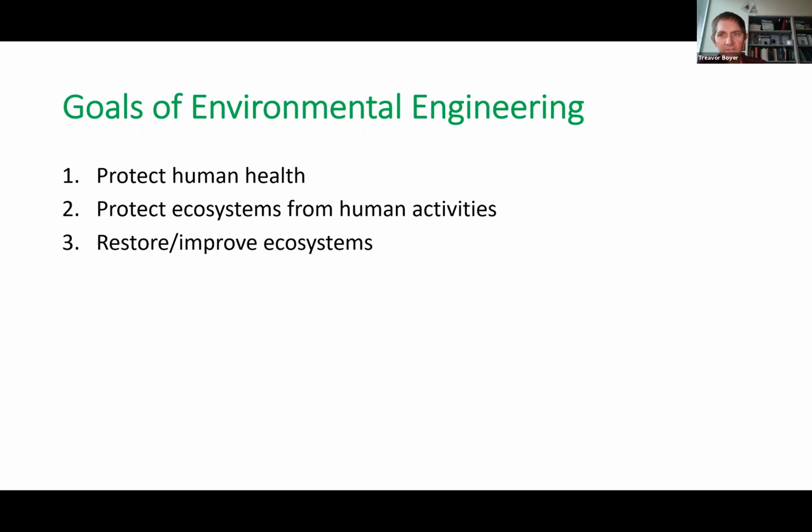All of what I've said so far was really about protecting human health. But the other thing is to think about the ecosystems involved. When you send untreated wastewater out into the environment, it obviously pollutes the environment. But one of the key things it does in terms of water quality is that it depletes the oxygen in lakes and rivers, because all this organic material that you release breaks down and depletes the oxygen. Then all the organisms, the fish in particular that live in the water, die because there's no longer any oxygen there. And so you get these huge fish kills.